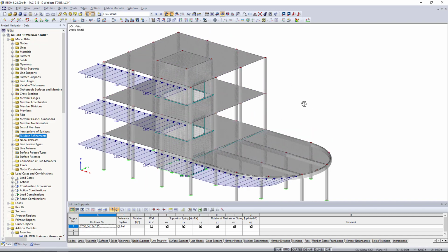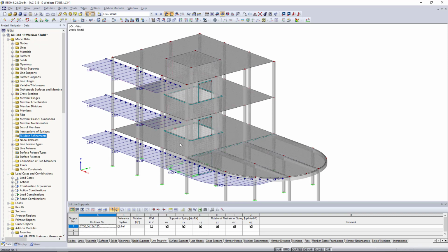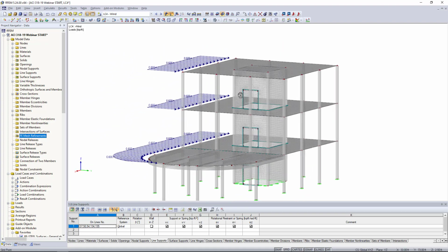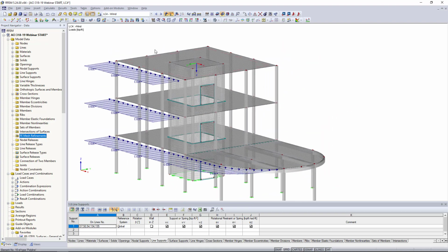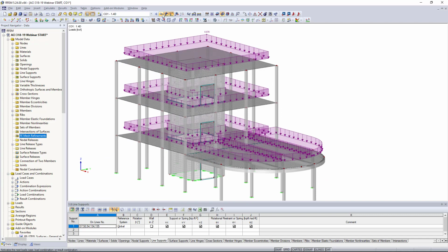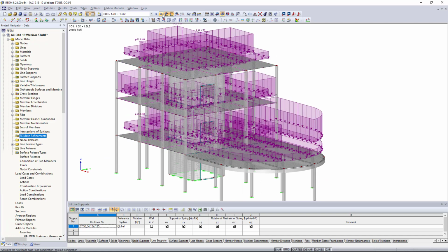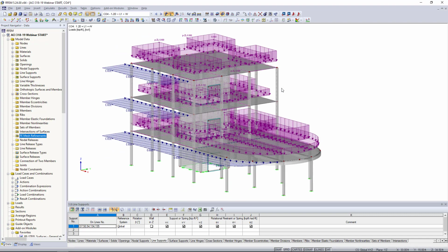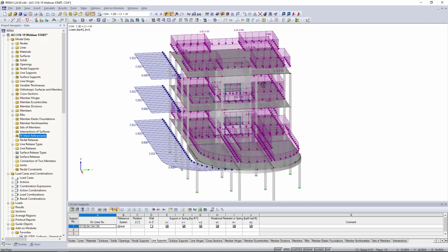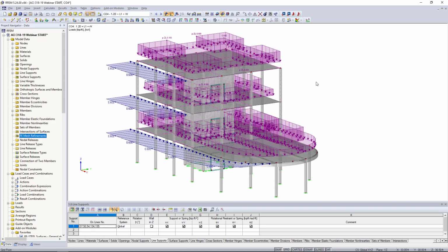And finally, simple lateral load just applied to every diaphragm level here, every story level in the global Y direction. So nothing too complicated. Now we can view our load combinations displayed together, which is going to show our dead load, our live load, and our wind load acting on the structure.